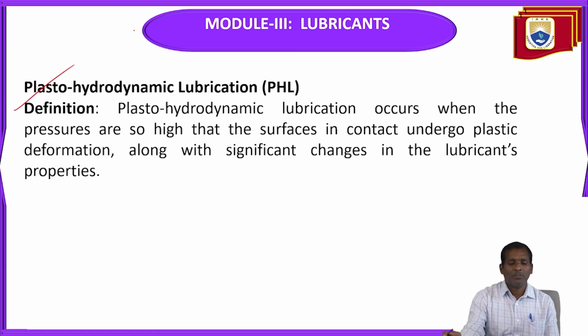Next one is plasto-hydrodynamic lubrication, PHL. As per definition, the plasto-hydrodynamic lubrication occurs when the pressures are so high that the surfaces in contact undergo plastic deformation, along with significant changes in the lubricant's properties.